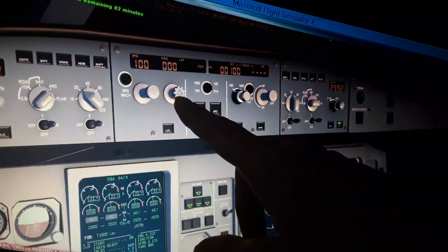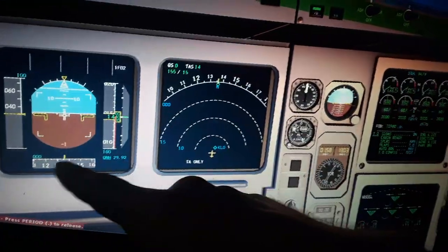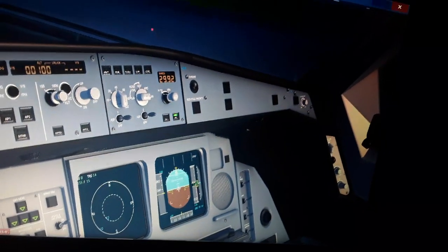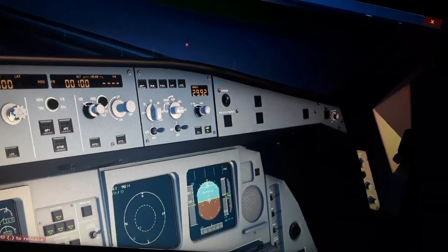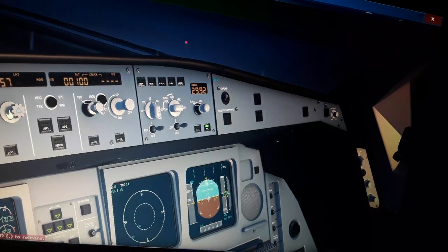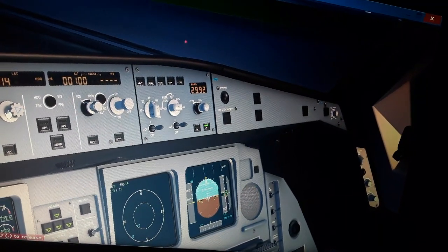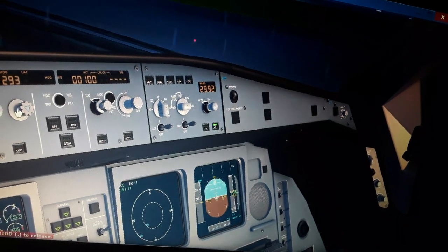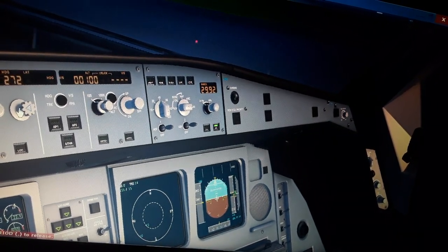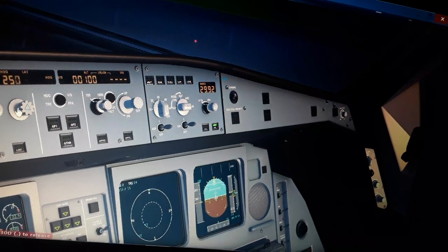The heading of 0 or 360 degrees is also displayed here. We can change this to the runway heading actually, or we can leave this managed for the system. So if I'm gonna change the heading to the runway heading of 135 degrees, I believe.